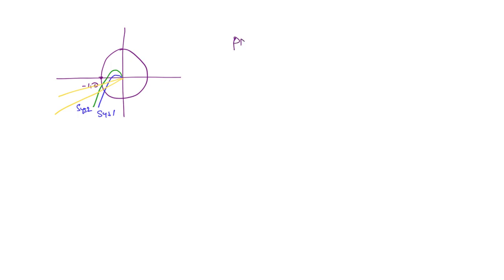What about the case of relative stability? If you take two systems, both of which we know are stable, let us say this is one system and this is the other system. Then what will the phase margin be if this is system 1 and this is system 2? Which system will have a higher phase margin? You can draw the lines here and compare. So clearly you can see that the phase margin of system 2 is less than the phase margin of system 1. So system 2 is more stable. This is how you decide: the more the phase margin, the more will be the stability. This is how you decide the relative stability.